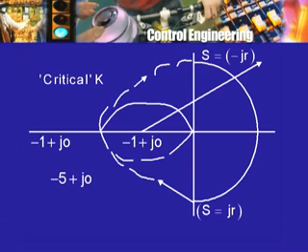So, do not just plot this part and rush to any conclusion about stability. Complete the full image and then only proceed to apply the Nyquist criterion, and of course, at the base of it or behind it is really the principle of the argument. So, remember this, these possible errors that one can commit by not paying attention to some of the important aspects.